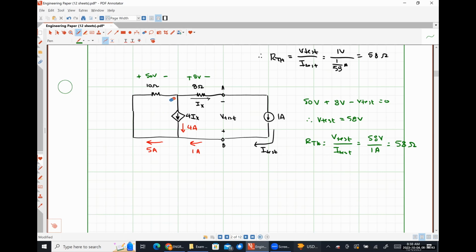All right, so let's recap what we've talked about today. To find the Thevenin voltage, the process is literally exactly the same as if the circuit didn't have any dependent sources in it whatsoever. You're simply finding the open circuit voltage drop across a set of terminals for whatever case we're looking at. The Norton current process also did not change at all, right? So the Norton current is still just the current flowing through the short-circuited set of terminals of interest, okay?